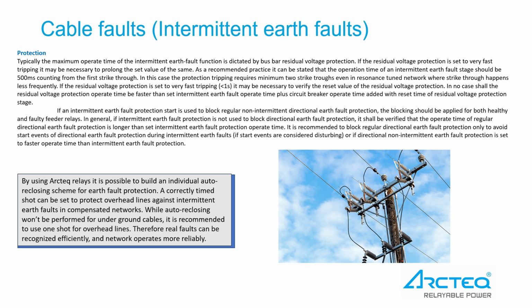If the residual voltage protection is set to very fast tripping, it may be necessary to verify the reset value of the residual voltage protection. In no case shall the residual voltage protection time be faster than the set intermittent earth fault operate time plus circuit breaker operate time, added with the reset time of the residual voltage protection stage.